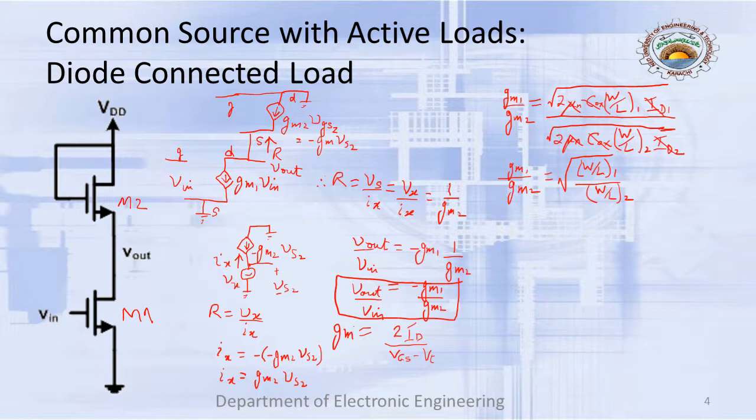The DC side is grounded. We are going to connect the gate and the drain together, and the source is connected down to the drain of the transistor, which is the lower one, and then here we have the input. The source of the lower transistor is grounded. So this is the input voltage, and for this, let's say we have gm1 vin. This is the gate, the drain, and the source.